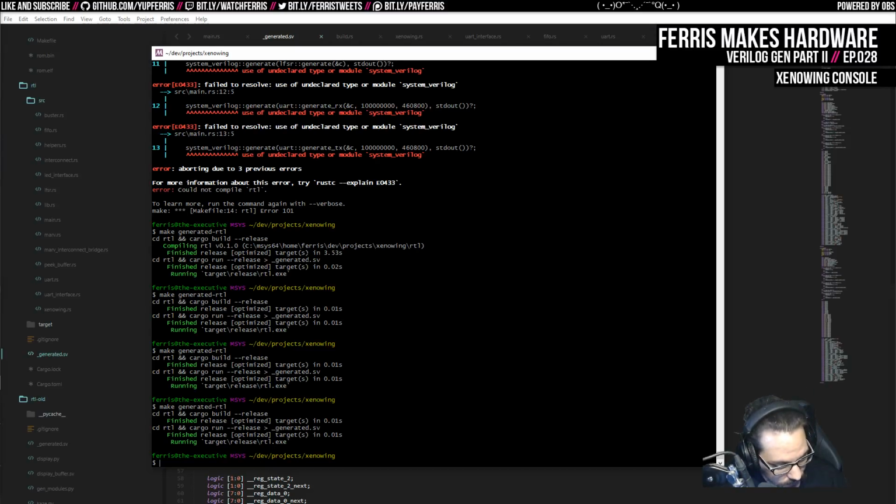the Uart receiver, and it didn't work on the actual hardware, and we started throwing things together, some tests, and looked at some output. I think I had hacked together some waveform generation, and the waveforms looked really good. So I was able to continue that debugging into the weekend. And long story short, the Verilog generation was bad.